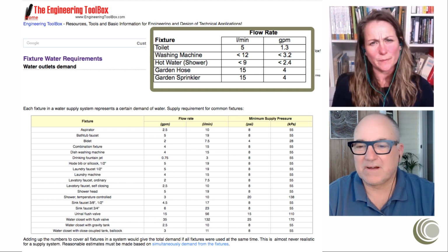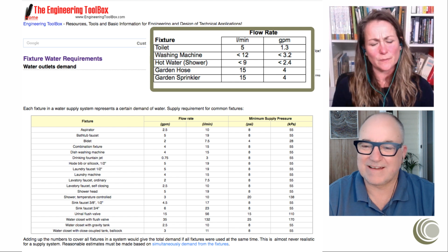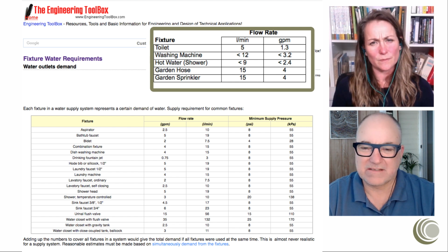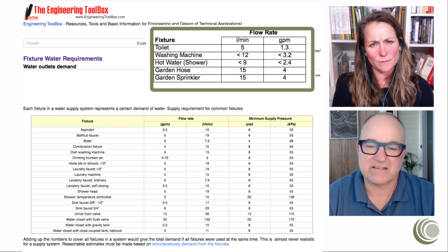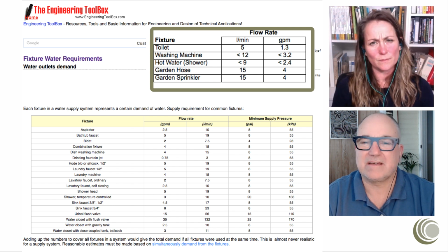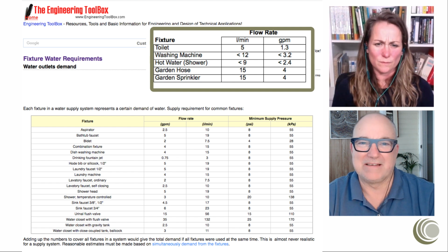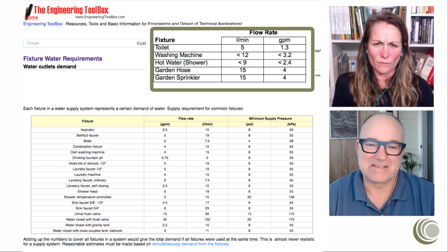The general rule I'd use, just in a normal house situation, is to work to minimise the number of bends and the length of supply to each of the end users. You know, washing machine, toilet, garden, whatever you're using it for, and that will minimise your losses, which is easier than trying to do the infernal arithmetic of the losses at every bend and length in your system.